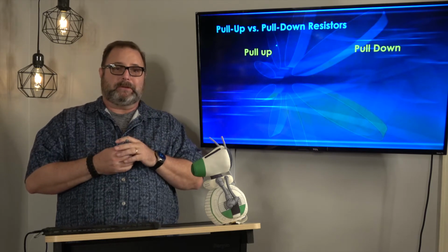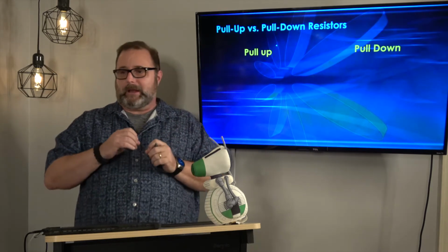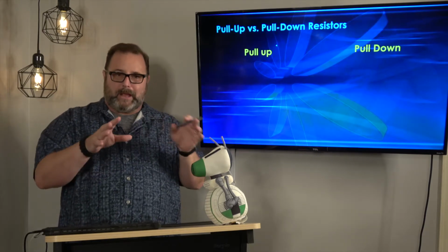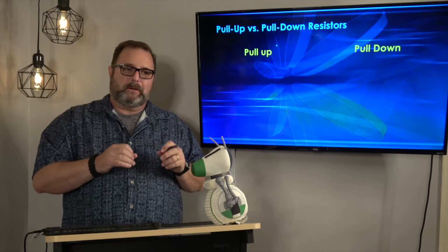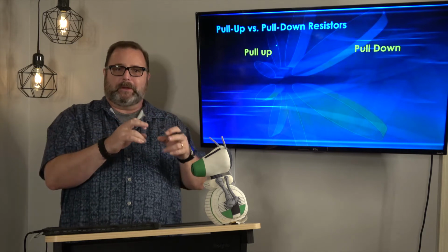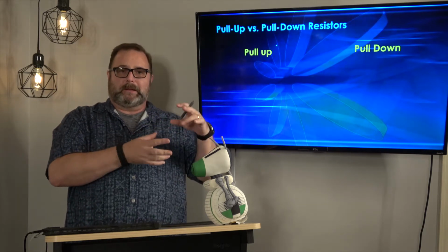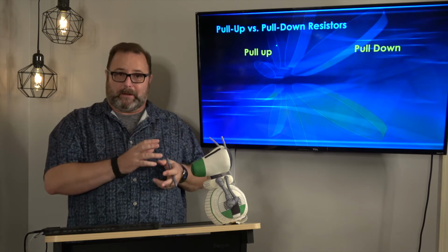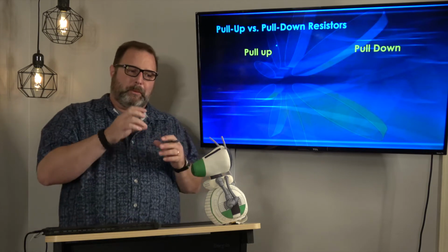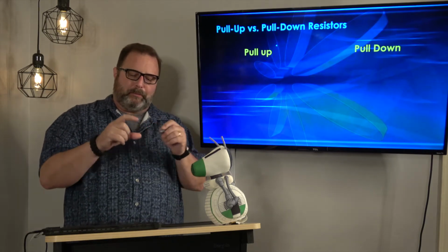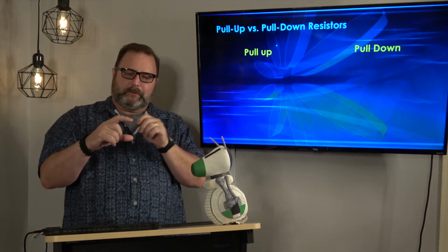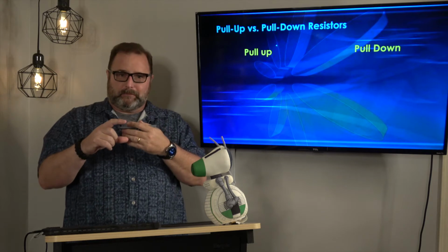Okay? And we will send signals to actuators and things on a robot and stepper motors and signals that need to be read. But another use is on NAND gates, NOR gates, AND gates, OR gates that make up the circuits that build us binary half adders and adders that allow computers to make calculations using binary. Okay? And what happens is if a particular gate doesn't have power to it, there's no input to a particular gate, the voltage across that gate can drift high or low.